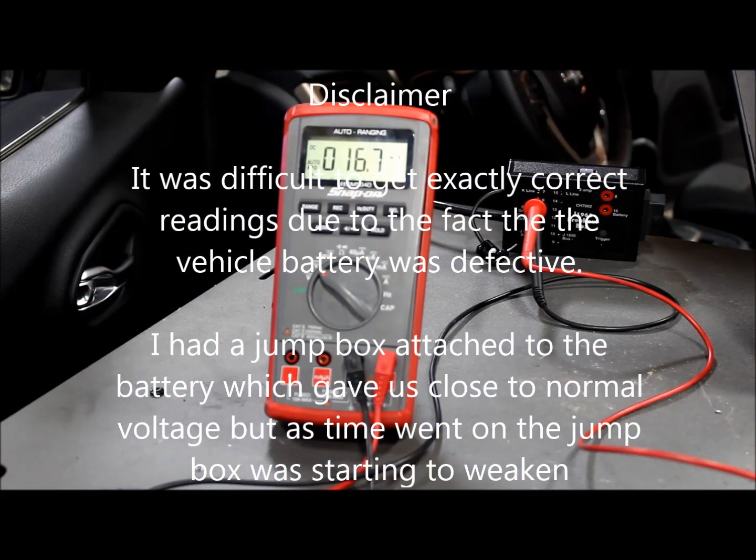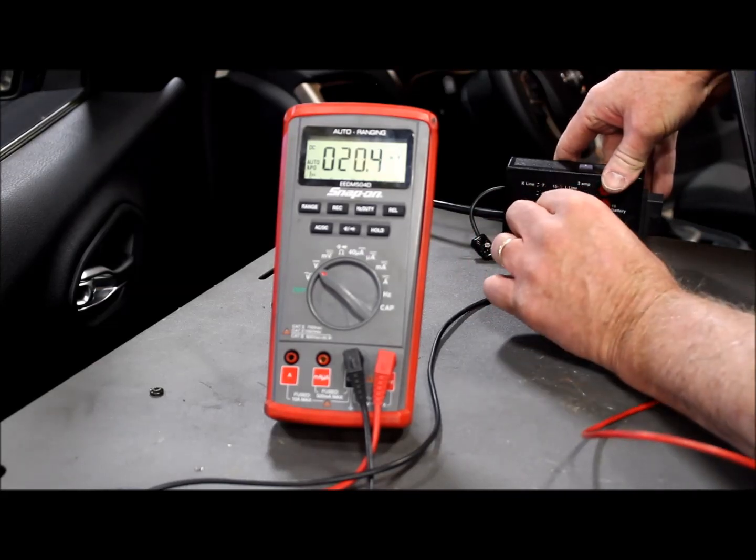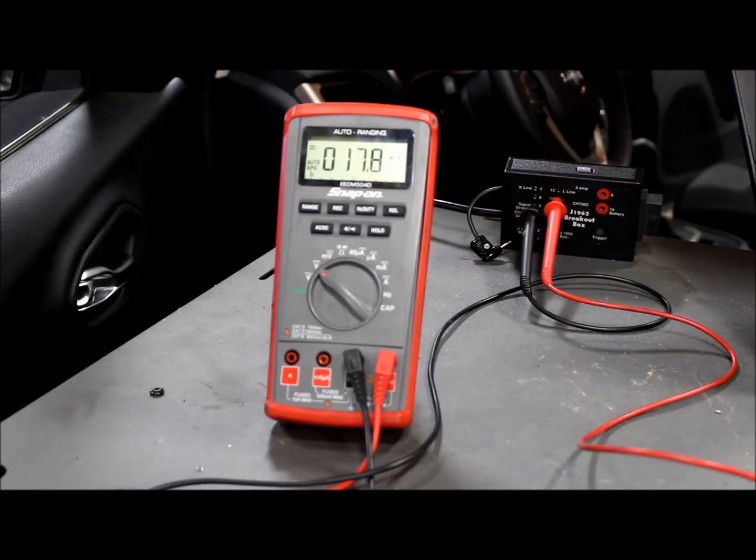So I've hooked the battery back up and I've switched over to volts. My common voltmeter lead, the black lead, I've put into pin 5. Pin 5 is the signal ground. And the red lead now, I'm in pin 6, which is the CAN-C plus. And it's reading essentially 0. It says 16.7 millivolts. The CAN low, or the CAN minus, pin 14, is essentially reading nothing also.